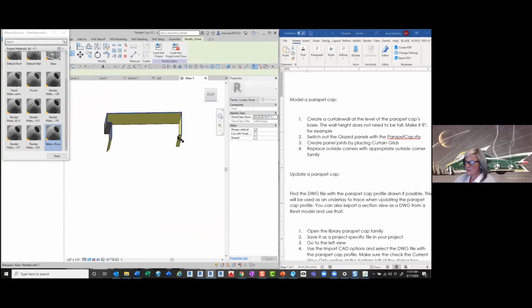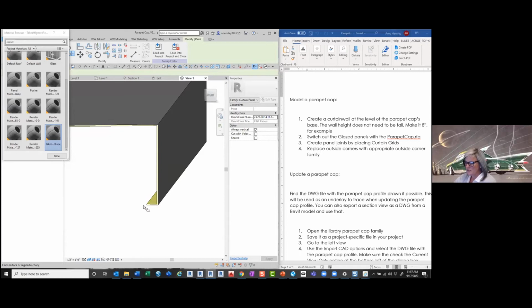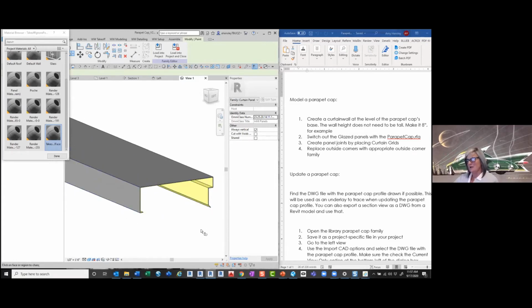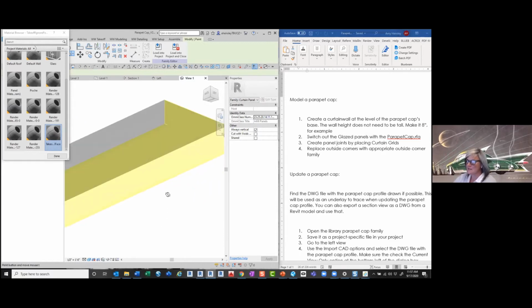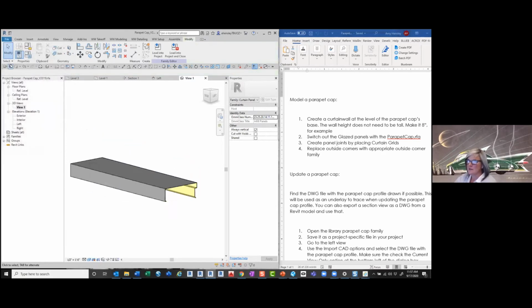And again, things like the tabs can change. That's why we're not going to totally worry about them right now. Designs change, details change. So if this changed and got deeper, we don't want to have to go back into the part family and update it and put it through the takeoff program and run it through all those routines all over again just for a tab change, right? So just leave it a default 1 inch. And when the panel team goes to work on this, they'll look at the details and see what it needs to be at that point. That's the kind of stuff where you go just enough into your modeling to get what matters in there, because it's probably going to change downstream. That leaves it flexible, and that leaves less change management to have to go back too far. Once you've finished painting those surfaces, you can just pick the Done button and it'll close you out of that command. And then you save your part.